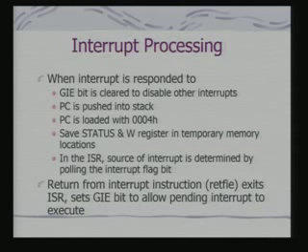And this pending interrupt might have set the flags, and should have set the flags, and again in the ISR you can check the flag to determine the interrupt. So, actually what you find here is that your interrupt handler routine for specific interrupts should be jumped to or called based on the flag bit that has been set, and that flag bit is checked inside your interrupt service routine.